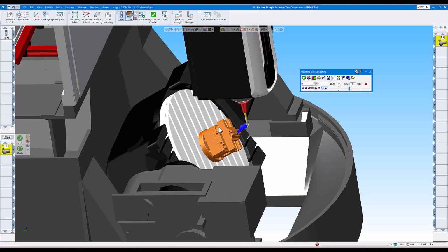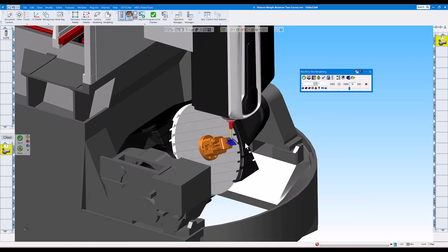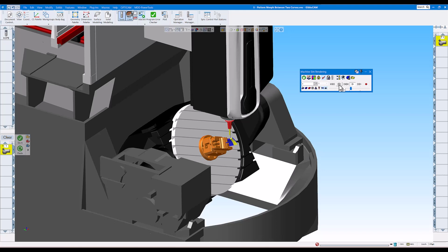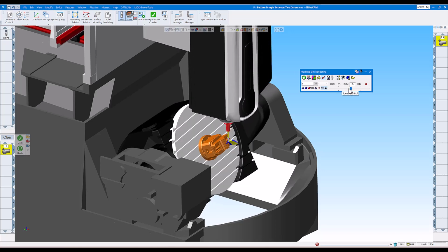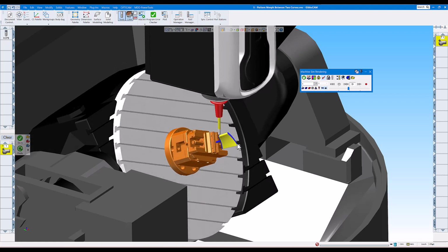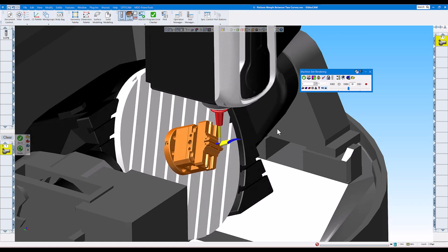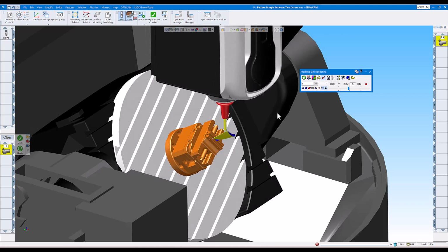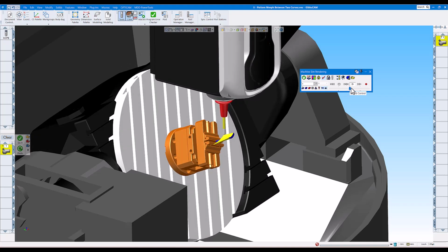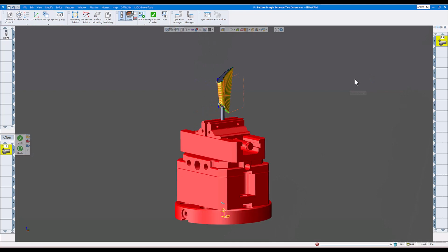And with this machine as well, you can do work area limits to keep it always on the front side of there instead of going to the back side. That way it's easier to see, helps to avoid collisions, especially if you can't see it. As we're finishing up there, and there's our arc off. So morph between two curves.